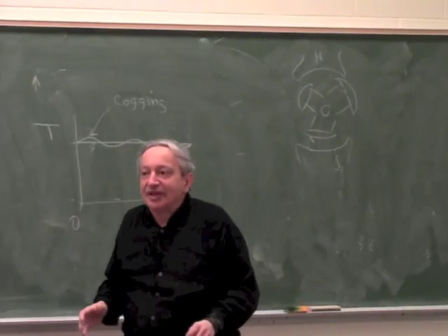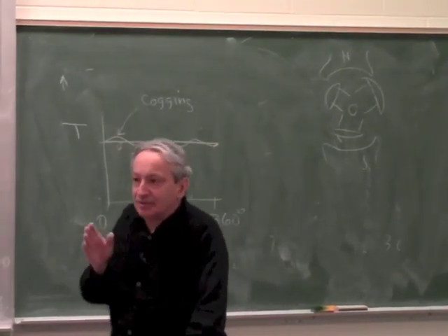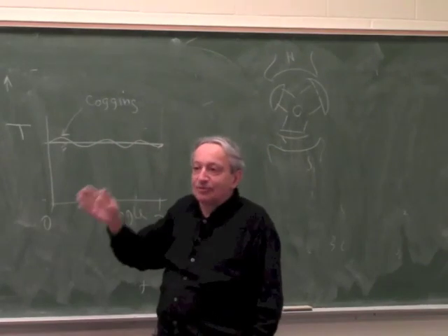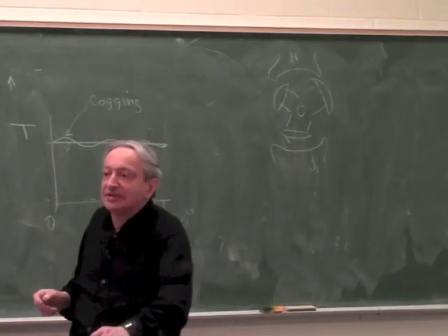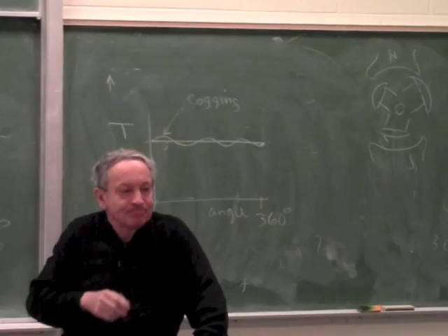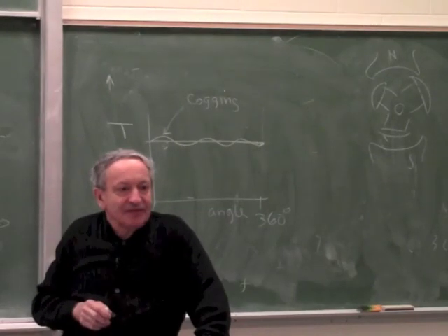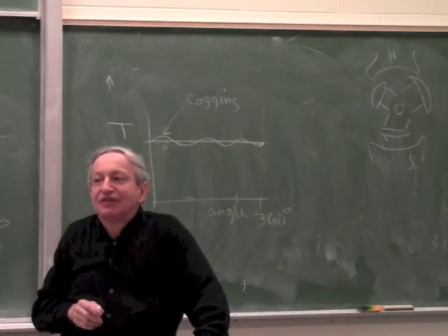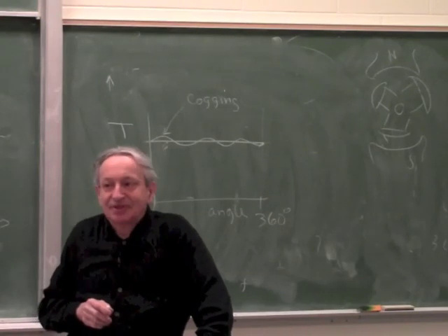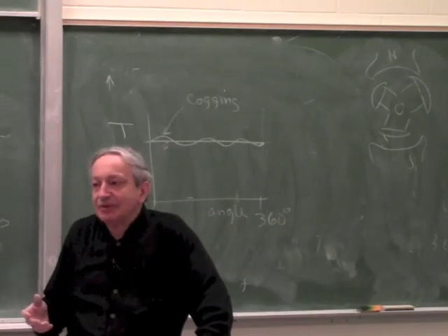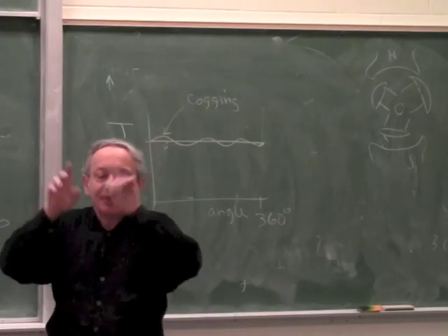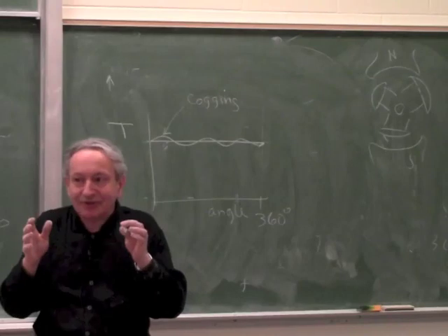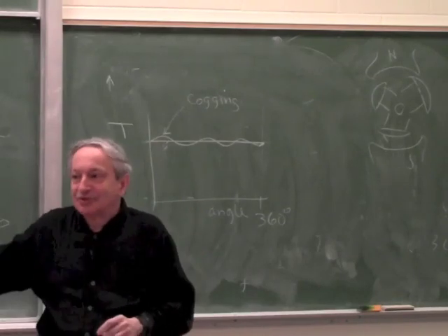So why do we care, actually? Because the servo system is going to position it. If the motor has an encoder, the servo will position it correctly, so why do we care? Non-linearity in the control? Correct. It's actually not even non-linearity, it's fluctuating gain. Because we give it a current, we want to have a torque. So if we look at the block diagram of the whole servo, there is a block there, which is the actuator. Input is current, output is torque.